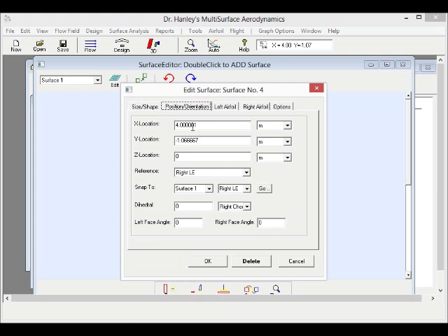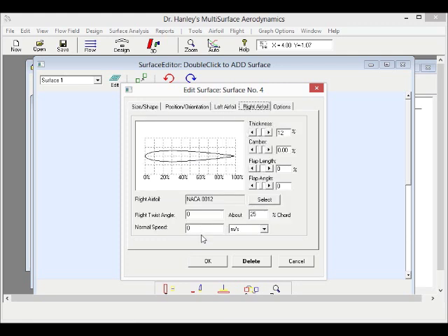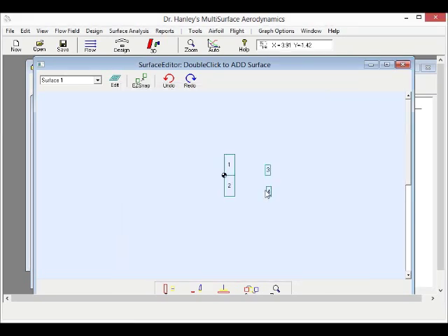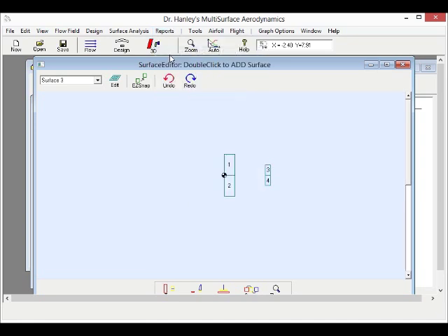So with our analysis, we saw that the wing by itself is not going to be stable, it's not going to trim. That suggests adding some more surfaces, and here we are looking at adding a horizontal tail section, horizontal stabilizers, and we can then go and do a longitudinal stability analysis for that combination.